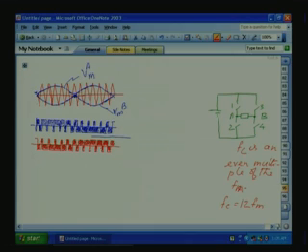What will happen to the harmonics, which is 12 times, an even multiple? 180 into 12 will be 360 degrees, that will be in the same phase. So all the harmonics at FC and its sidebands will be in phase, but the fundamental is in opposite phase. If you see the subtraction, the final will be a pulse amplitude of VDC in the positive direction. So you will get something like this.